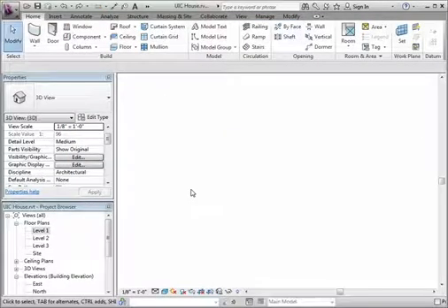It's important for you guys to understand one thing about how I'm working right now. I described to you earlier that when you're working in Revit, there's really one file. It's called the central file, and when you work as a group, everybody creates their own copies of that, called user files, and they work in the user files. Since I'm demonstrating this as just my own project, and since you guys are working on your own projects, you can consider that you're actually working in the central file, which, if you came into an office and started working in the central file, would probably be your last day in the office. So it's just good for you guys to understand how we're working.